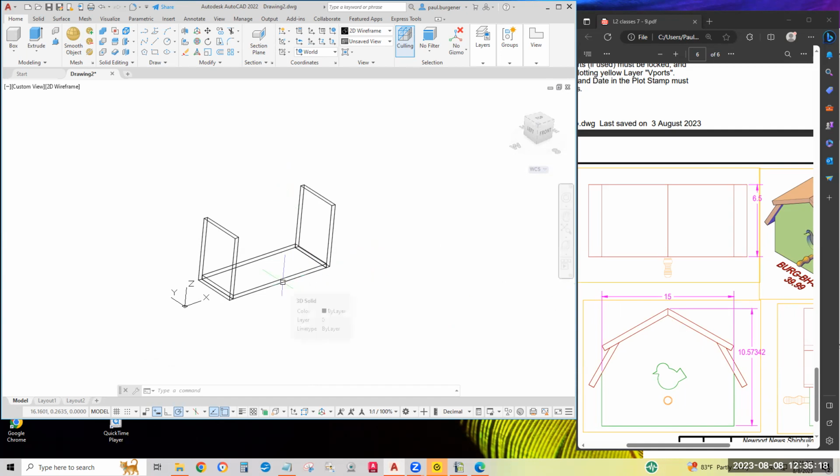All right, so let's draw a guideline from the XY plane midpoint of the floor here, straight up, say 10 units. Draw a line. We'll O-snap at the midpoint on the front bottom of the floor. We'll go straight up and make it say 10 units straight up, enter. So that'll be the peak here. How high do we want to go up the sides? I think we figured about 5, about half the height.